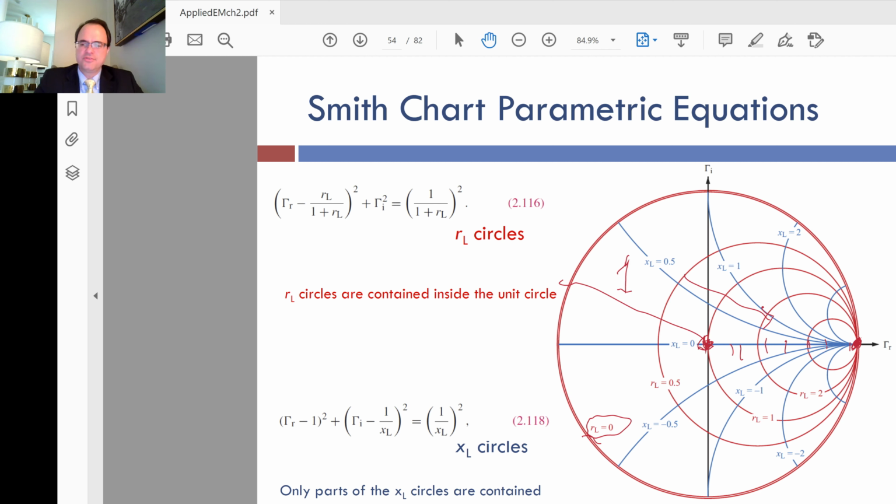So on the Smith chart, we are going to plot a family of curves for different RL values, starting at R sub L equal to 0 and getting to be progressively higher numbers, always greater than 0, so always positive values. No passive microwave circuit has a normalized resistance that's less than 0.